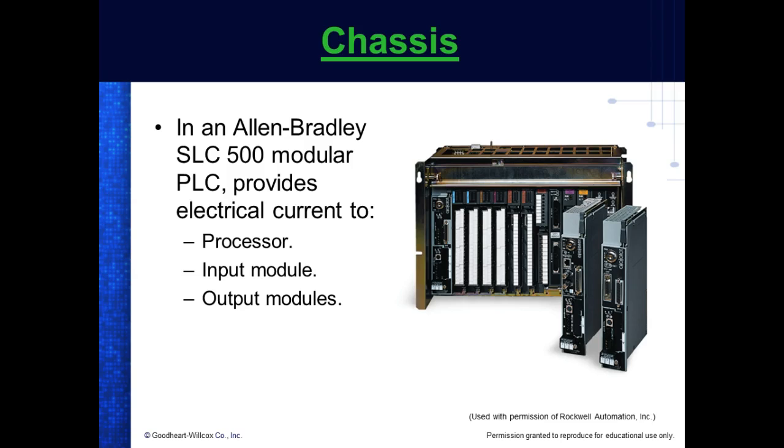This is the predominant power. PLCs have been around a long time. So you can get them that run off of 240 volts. I've never seen one that runs off 440, but you can get them that power up off 240 AC. You can get them that power up off 120 volts AC. You can get them powered up off 24 volts DC. And the book talks about 120 volts DC, but I've never seen that. But it don't mean they don't exist, right?